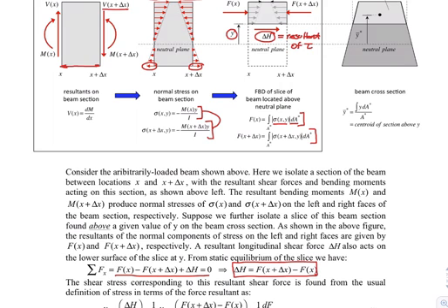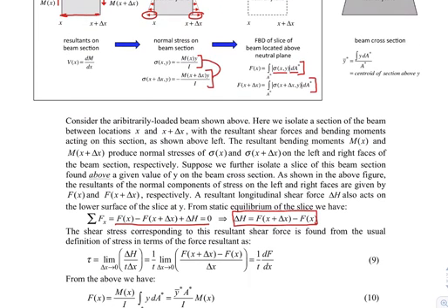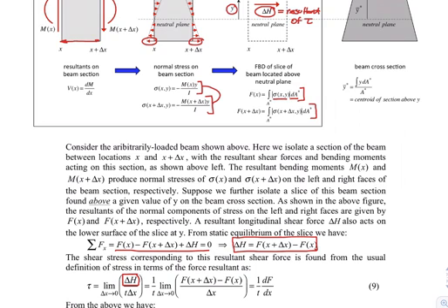resultant shear force is the difference between the resultant forces due to the normal. So here we begin to see our connection between the bending moment M and the shear stress that develops in that beam. Then we go back to our definition of what a shear stress is. We take the resultant force, that's that resultant force of delta H there on the bottom, up here.